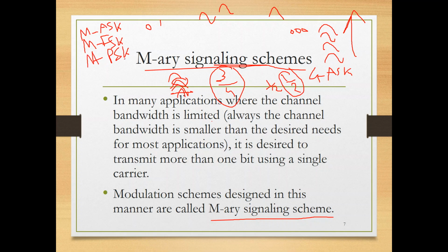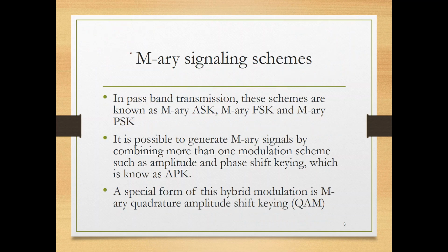M phase shift keying, you use different phases. What's the good thing about phase shift? Each one has a key property. Phase shift keying, constant amplitude, good for peak to average power ratio, power amplifier. Amplitude shift keying, good when you don't have too much noise. Phase shift keying, good when you have interference and noise. So what works for a certain scenario cannot work for the other scenarios. This is the beauty of it, that you have freedom in selecting between them.